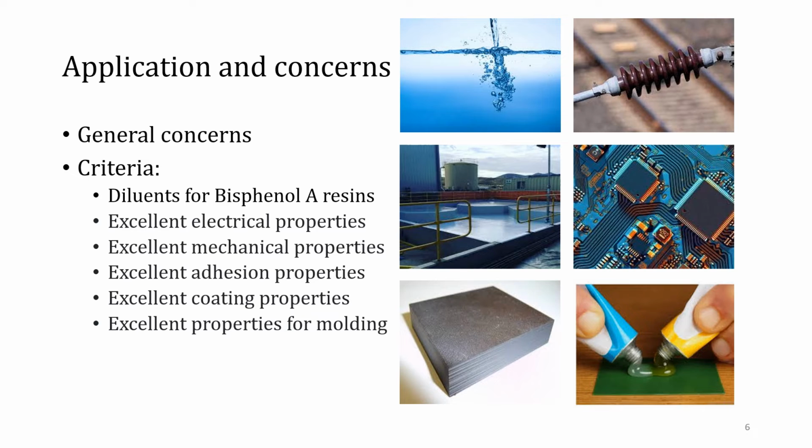UV curable coating has been paid more and more attention for its advantages of fast curing, no need of high temperature, no generation of bubbles, and good film growth. This kind of coating prepared with cycloaliphatic epoxy as the main component has strong weather resistance, high hardness, wear resistance, impact resistance, chemical and corrosion resistance, and good adhesion. They can be used for printed circuit boards, solder resist inks, optical disc coatings, and metal and plastic cover protection.